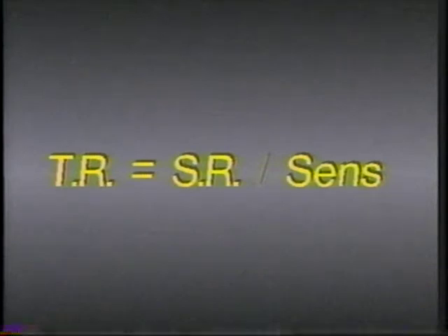Knowing the system sensitivity allows us to establish a throttling range, which is defined as the total temperature change necessary to completely modulate the valve from fully open to fully closed. The mathematical expression for throttling range is spring range divided by sensitivity.